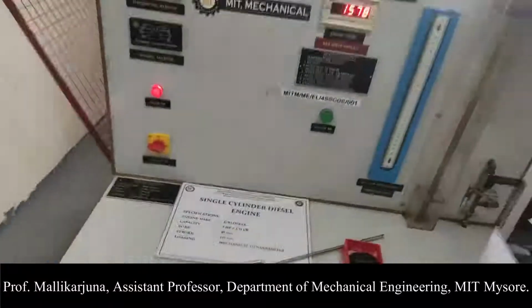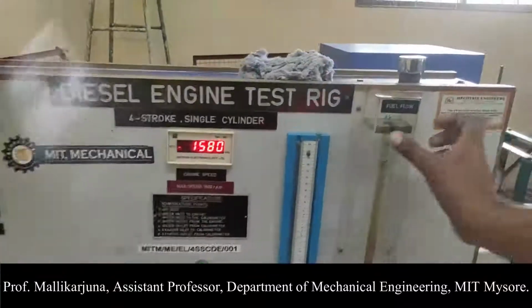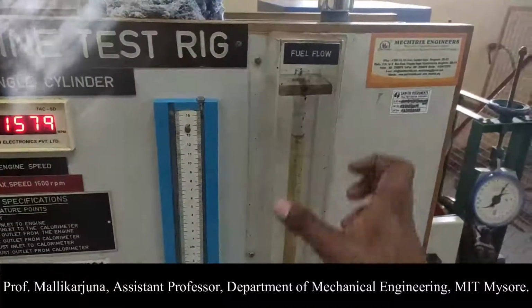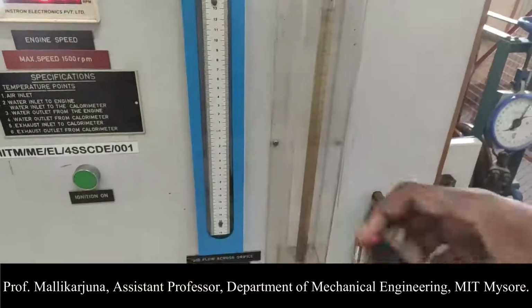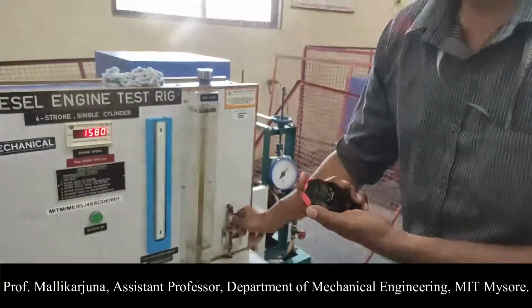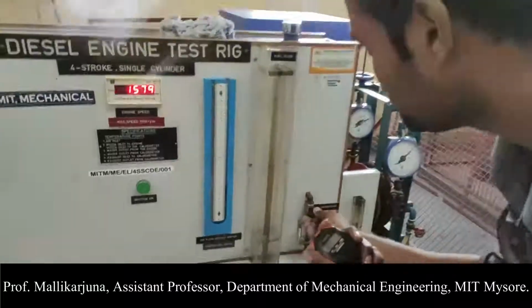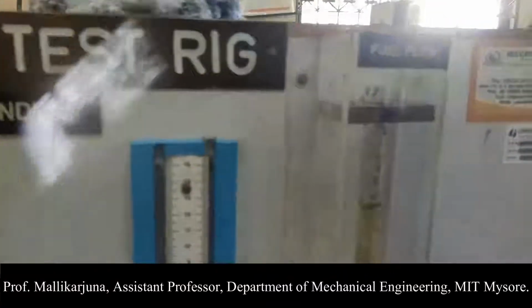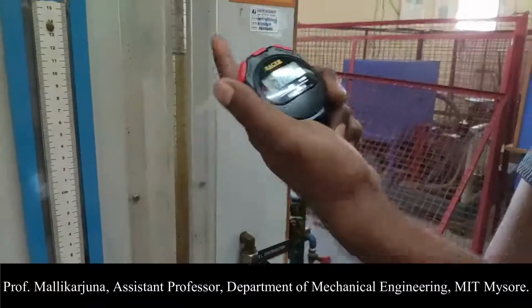Now we need to look onto the various other aspects. Here is the fuel supply indicator. Now we need to look onto the time taken for 5 cc of fuel consumption. So now I am switching on this. Please note the time taken for 5 cc consumption of the fuel. Now I am starting the timer from 5.